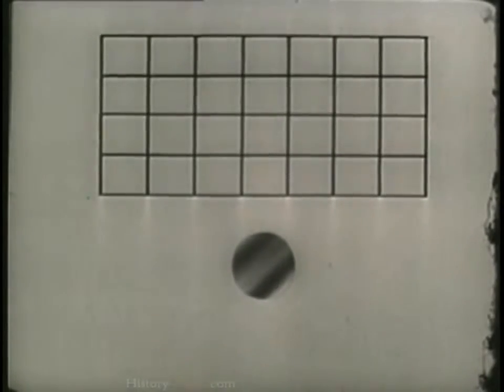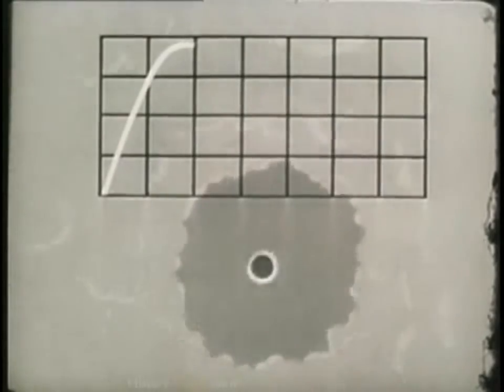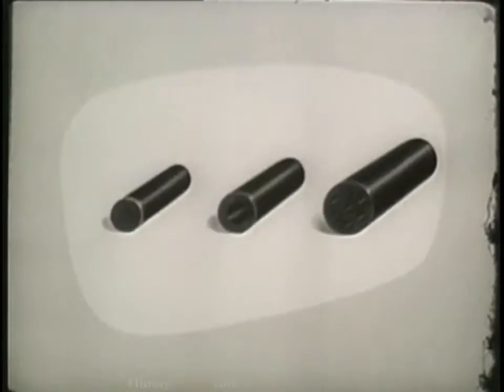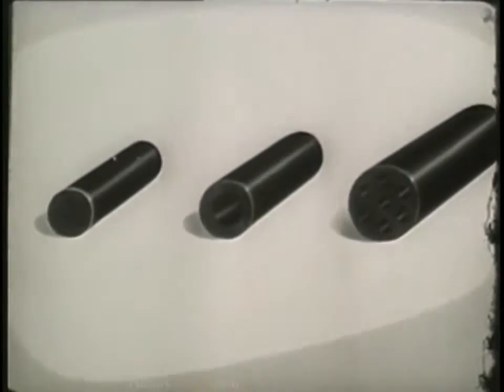As the burning surface decreases, pressure is generated at a slower rate. Here's a graph to show pressure action during burning. The degressive grain produces a very high pressure quickly, but the movement of the projectile tends to let the pressure drop off rapidly.